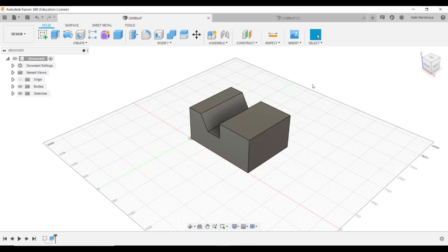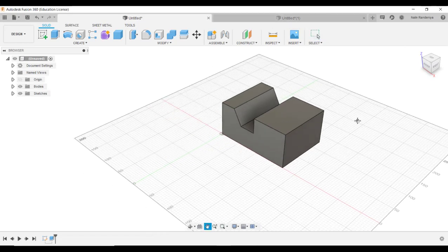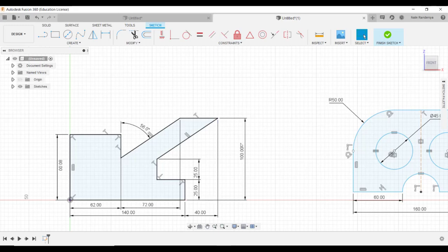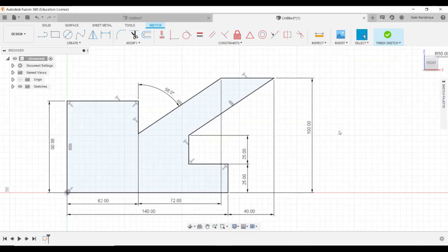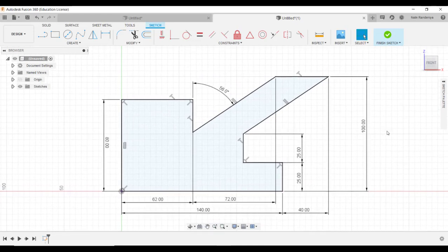Meanwhile, before you start that video, I would like you to try this exercise. Using the sketching knowledge you acquired in this video, I would like you to create these two sketches here. They are fully defined. I have given all the dimensions. The main advice I can give you is, first, do not worry about the dimensions. Don't just draw a line and give 140 to that, another line 25. Nope, not like that. Just draw the basic shape with the lines the same way I did in the video. After that, as a second stage, give the necessary constraints. After that, you can give the dimensions.